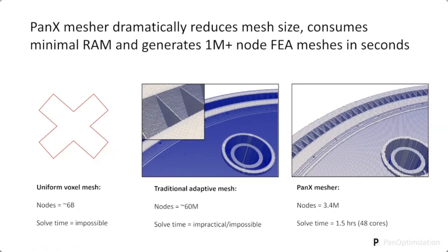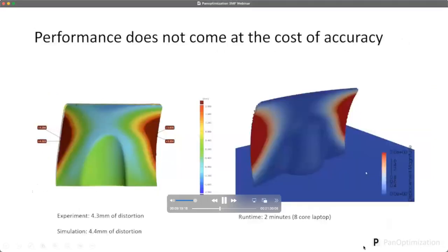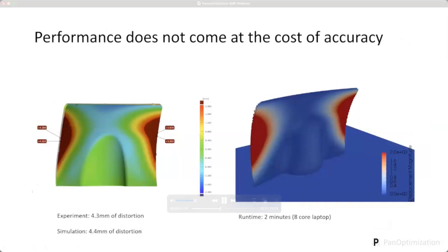When we started to see these results last year, I think we were pretty excited with the potential for this. The next thing I'll touch on is that when we use that meshing approach, we're just trimming fat. Those voxels that aren't appearing didn't have any value. They were just slowing down our computation time. So we can still get very accurate results with this meshing approach. So here's an inherent strain simulation we did.